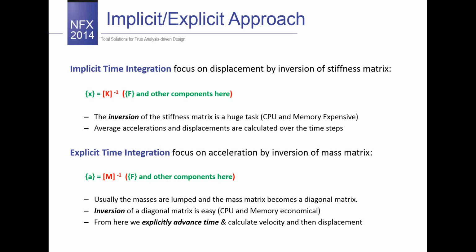So now just to remind you, I'm talking about the dynamic analysis. So at this moment let's forget for a while this quasi-static. Now I'm talking about the dynamic approaches, actually. If we consider the implicit time integration, we have to remember that this method focuses on the displacement by inversion of the stiffness matrix.